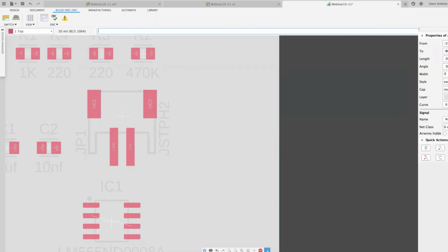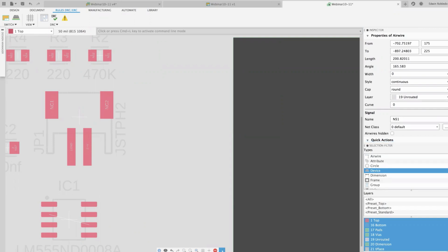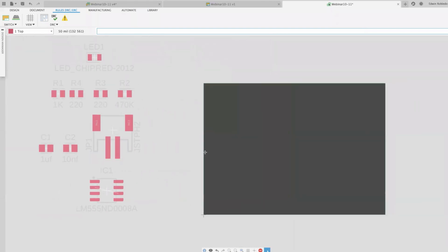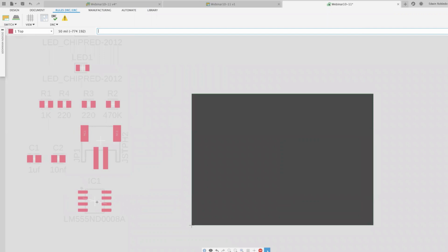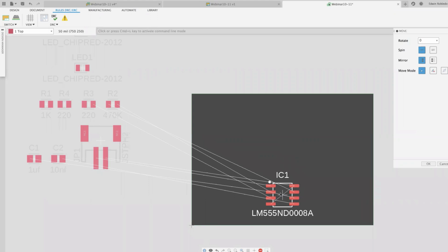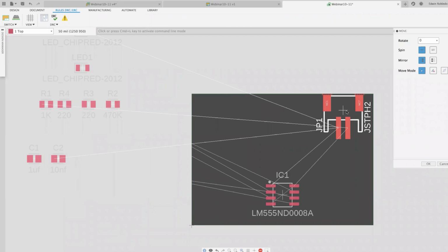So you know what? I'm going to show you a little bit of how to use the selection filter here. Let's go ahead and enable this, and I'm going to tell it that I want it to allow me to select components. Let me find the components here. My selection filter should be device here. I'll hide this one more time because I no longer need it. Now, when I start selecting components, it will filter out anything other than a component. Now I can click here and select that component, as you can see. I'll go ahead and place one.